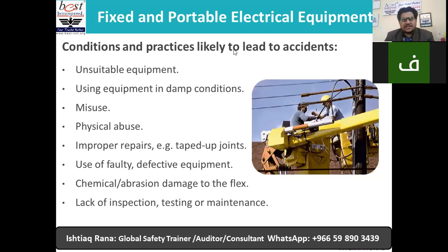Now, we have fixed and portable electrical equipment. Yes, it depends on the conditions and practice likely to lead to an accident. If that fixed or portable electrical equipment is unsuitable equipment, using equipment in damp conditions or even misuse would be another reason to create a disaster. So physical abuse or improper repairs, taped up joints, like temporary solutions.